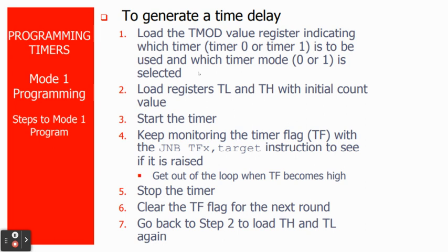Now, I will explain this more later on, but again, the TMOD, in other words for number 1, determines whether you're using timer 0 or timer 1, or you're using mode 0, mode 1, mode 2, or mode 3.